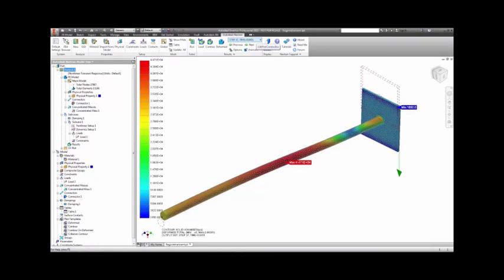On this stress plot, you can see that unlike the static analysis, the highest stresses are in the center of the pole. They are over yield, so the pole can be expected to acquire a permanent bend. Another result that's worth looking at from a nonlinear analysis is the plastic strain plot. The strain plot will tell you exactly where you've exceeded the yield point and how much the part has bent.